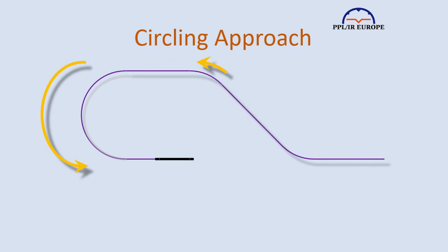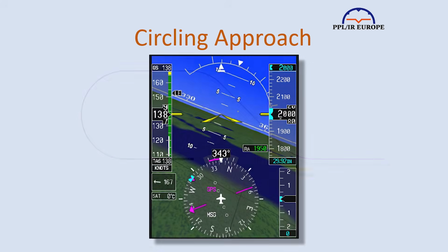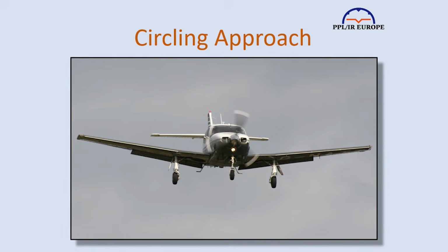The pilot should make left turns unless otherwise specified on the approach plate or authorised by ATC. This confusingly means that the first turn is to the right to establish in a left-hand pattern. In our kinds of aircraft, use rate 1 turns, or only exceed them slightly if you need to fly the turn accurately. Pilots should generally enter the manoeuvre in landing configuration, gear down, landing flap set, and maintain it during the circling phase to minimise workload and reduce omissions.